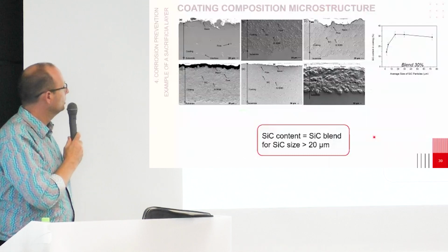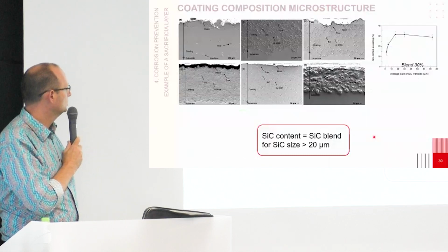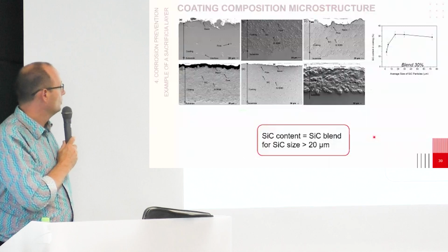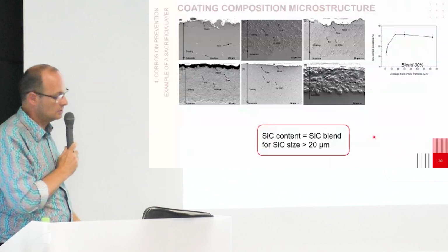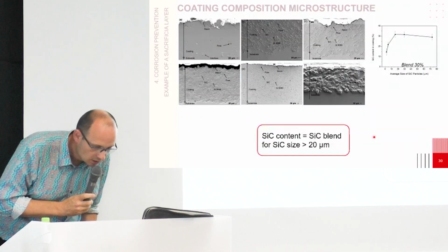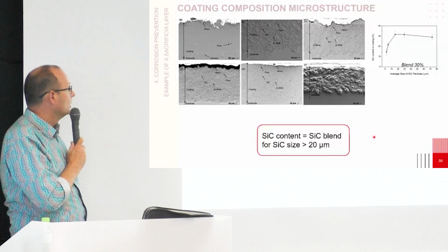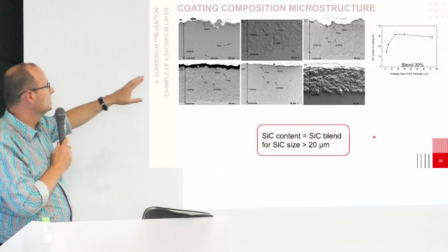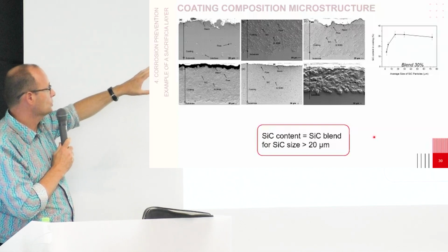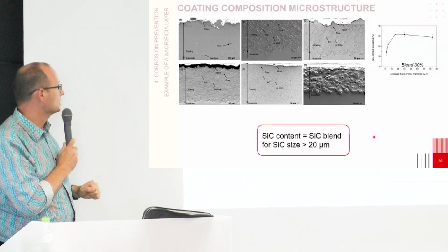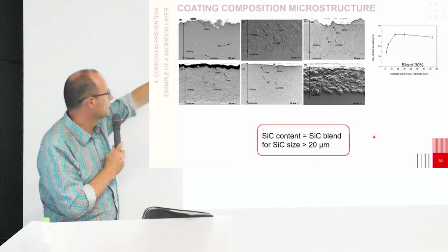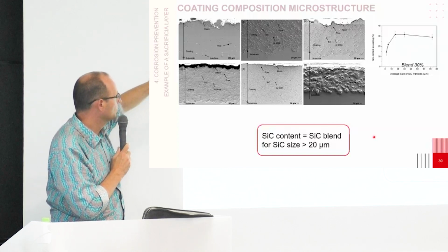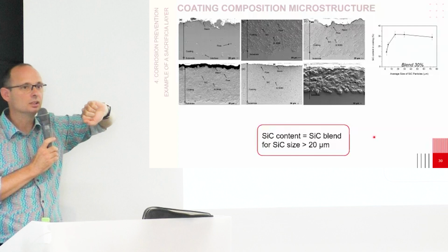And you look at the micrograph of the cross-section of the coatings that you get, and you look at defects. So where the reinforcing particles, so silicon carbide, are distributed, and you can start to have a map about, okay, I designed a coating.